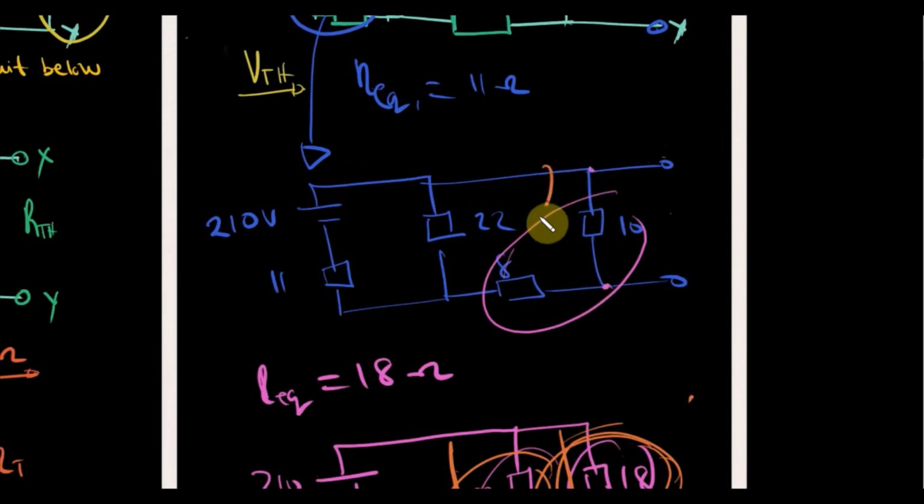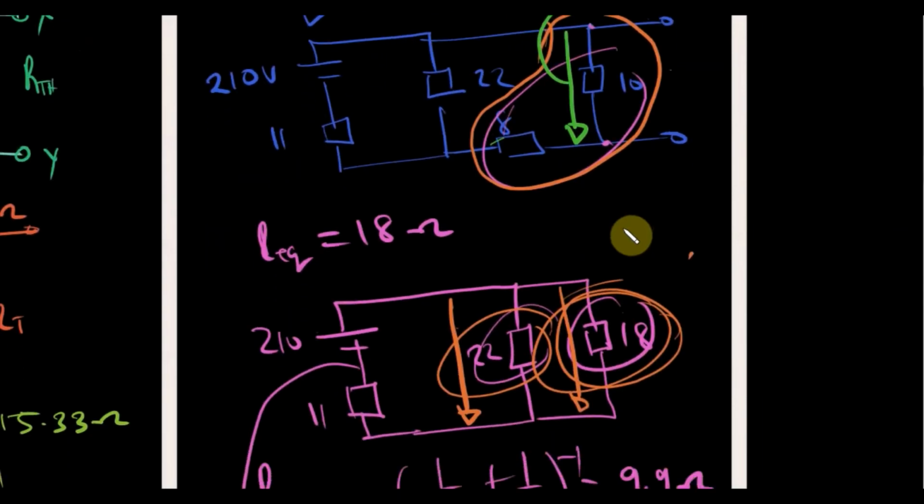If the voltage drop in the 18 ohm resistor is 99.47, we know that the 18 ohm resistor comes from adding 10 and 8, which are in series with one another. But our point of interest is what? The voltage drop that we really want is not the combination of 18 and 10. We actually want this one here. So let's just go ahead and get that. Since they are in series, we know the total voltage drop.